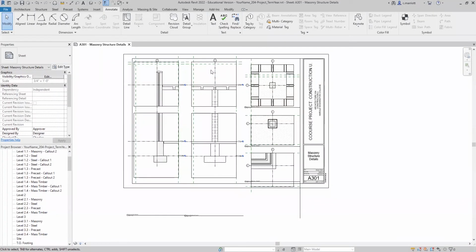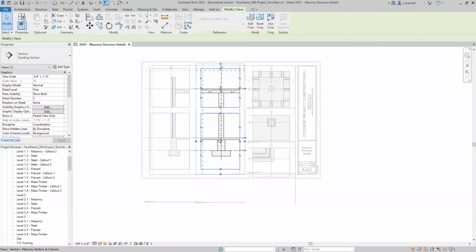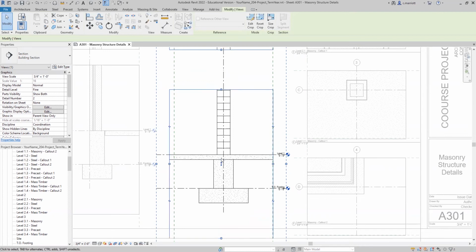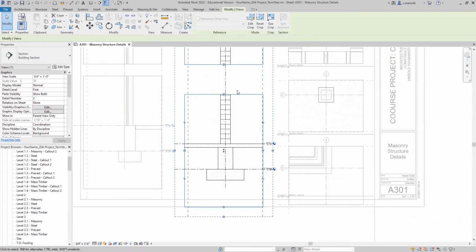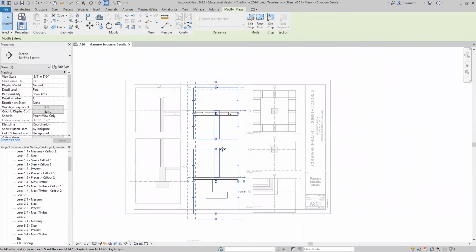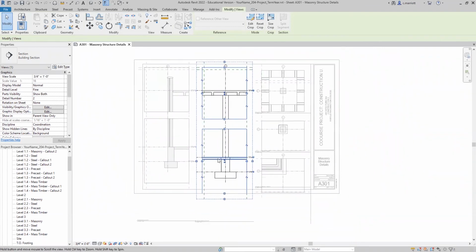Now, generally speaking, I would try to fill the whole space if you can with these two section details. So bring the footings down lower, and we'll also need to bring these title lines up. I'm in the editing mode for that section, and I'm going to use the arrow keys to bring it down a little bit. Now the detail above should stay where it is. And then I can bring these a little closer. Okay, so everything up above has stayed the same.